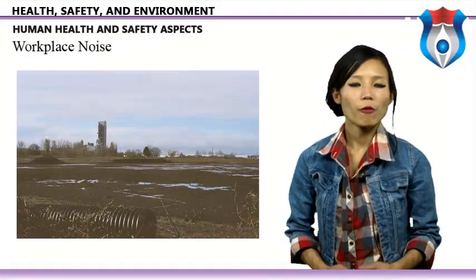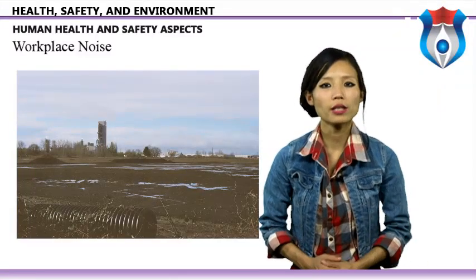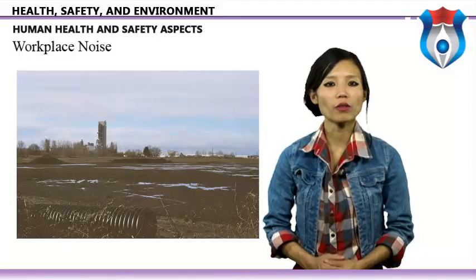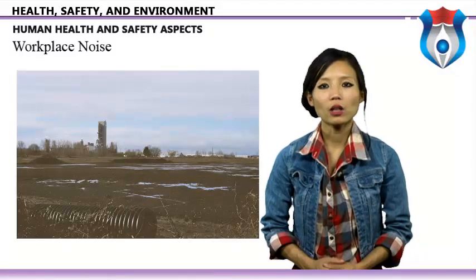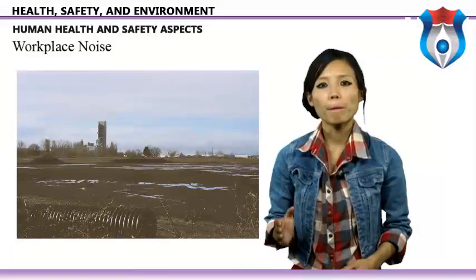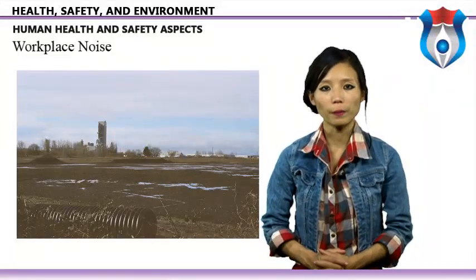Workplace noise. Feasible administrative and engineering controls, including sound insulated equipment and control rooms, should be employed to reduce the average noise level in normal work areas. Plant equipment should be well maintained to minimize noise levels. Personnel must use hearing protection when exposed to noise levels above 85 dB.